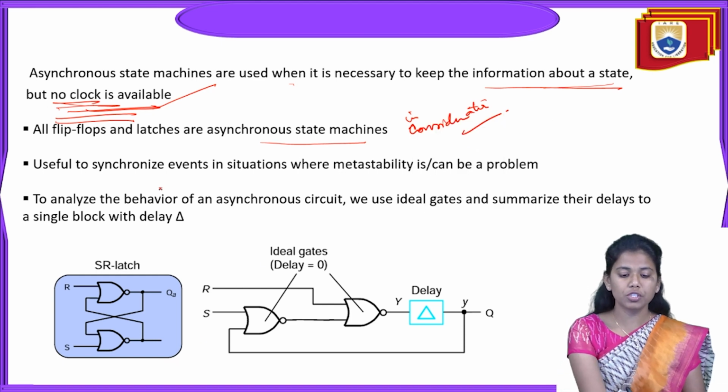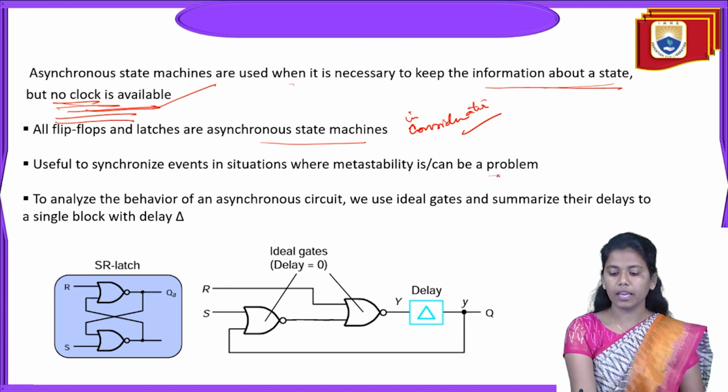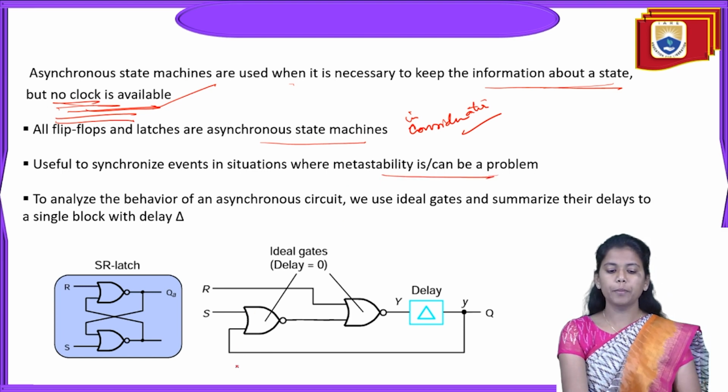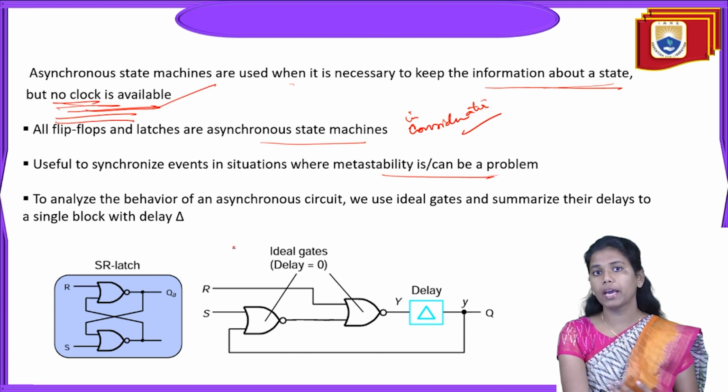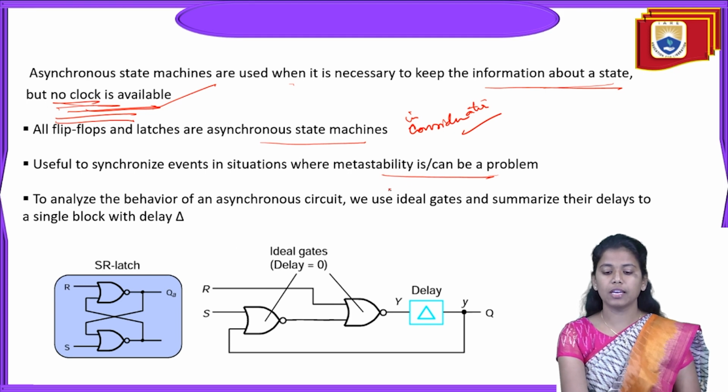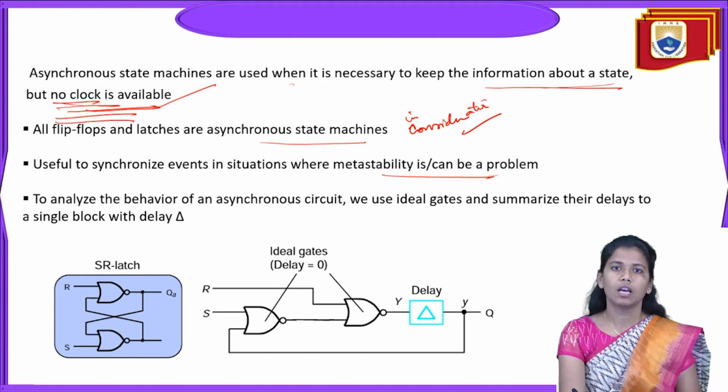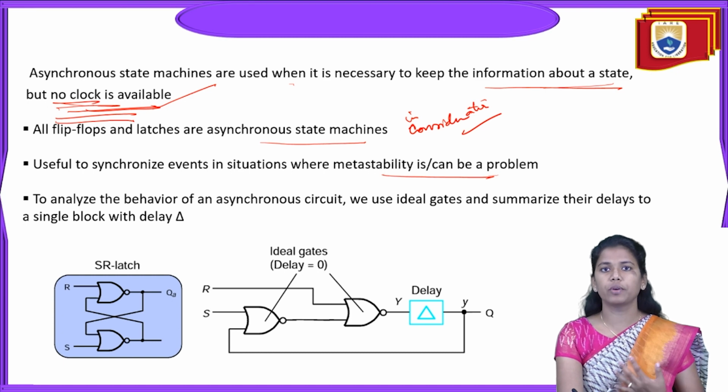So it is useful to synchronize events in situations where metastability can be a problem. If you are considering any sort of memory elements like flip-flops and latches, you may have to face the consequence that metastability can be a problem. Unless you are using memory or storage elements, it is well and fine.